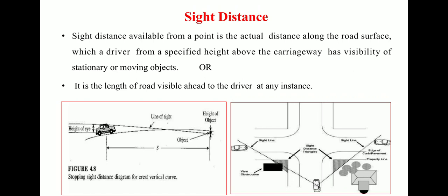Sight distance is the length of the road surface which a particular driver can see with an acceptable level of clarity. Sight distance plays an important role in geometric highway design because it establishes an acceptable design speed based on the driver's ability to visually identify and stop for unforeseen roadway hazards or pass a slower vehicle without being in conflict with opposing traffic. As velocities on roadways increase, the design must allow additional viewing distance and time to stop.